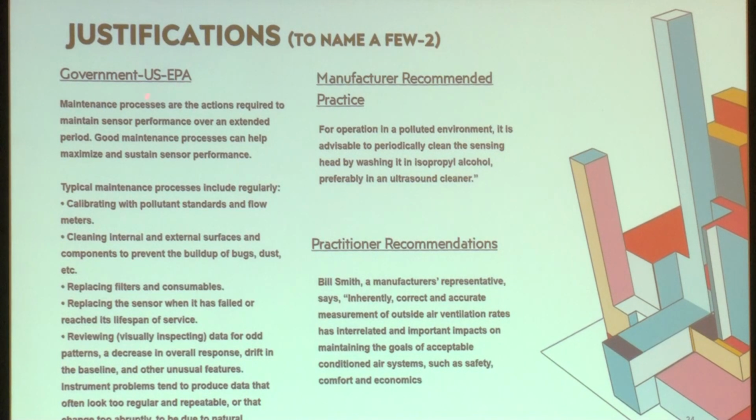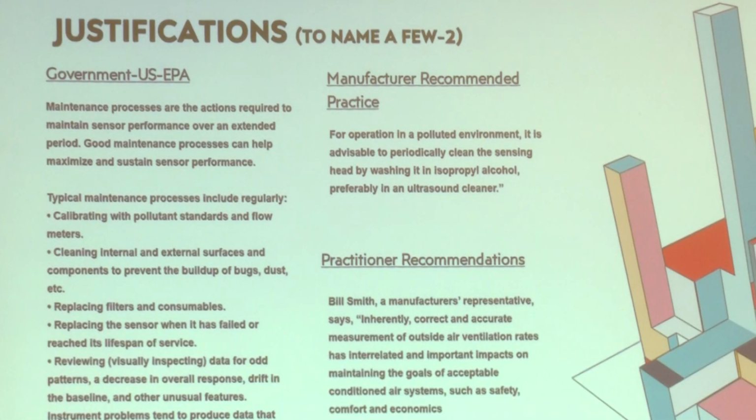Very good. The government says that we should do it. The government, the US EPA, says we should calibrate and keep everything working and operating per its practice. The manufacturer recommended practice says that we need to clean those devices and make sure they're operating properly. And practitioners, people that actually sell it, will tell you that yes, you absolutely need to keep the filtration of the air that hits their devices clean before it hits the airflow monitor. Otherwise, their airflow monitor will not work right.